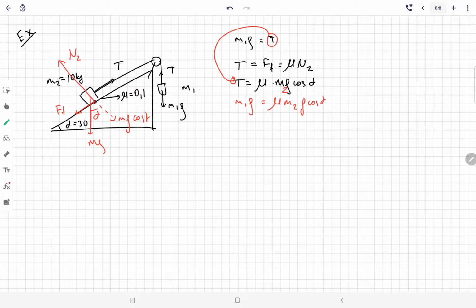And there is one force we forgot to mention, so it's my mistake. I didn't draw the free body diagram properly. So here downward we have a m2g sine alpha. As you see, if you don't apply free body diagram, there is a chance that you will make mistakes. So here we need to add m2g sine alpha. So be careful.